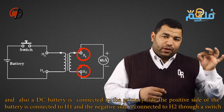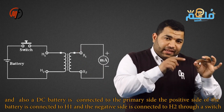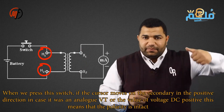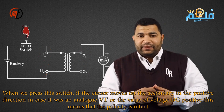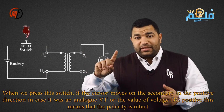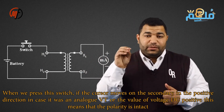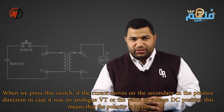Confirm values from the IR, winding resistance, ratio, and polarity tests, and ensure the VT wires to the panels are correct. Perform the VT secondary injection test. So when we press this switch, if the needle on the secondary moves in the positive direction in the case of an analog meter, or if the DC voltage reading is positive, that means the polarity is correct.